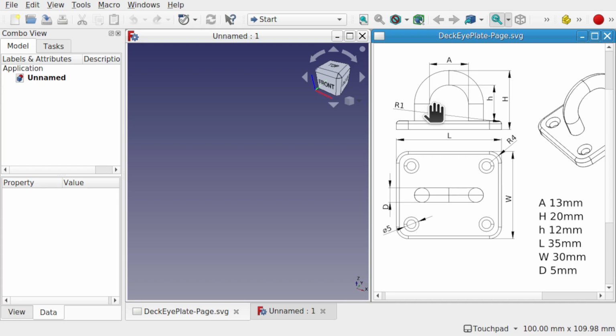Let's first look at a rotate workflow using the part design. We'll look at this in the part as well and show how both of those workflows differ using part design feature-based modeling compared to the part boolean-based modeling. What I'd like to do first is get an idea of the scale of the object by using some construction geometry in a simple sketch. And also we're going to be working out the basic sizes along here, because we've got this height, we've got the inner height, and we've got the dimensions of this, and we've got a few measurements that we need to work out. We can do this with maths, but I prefer to do it a more visual way.